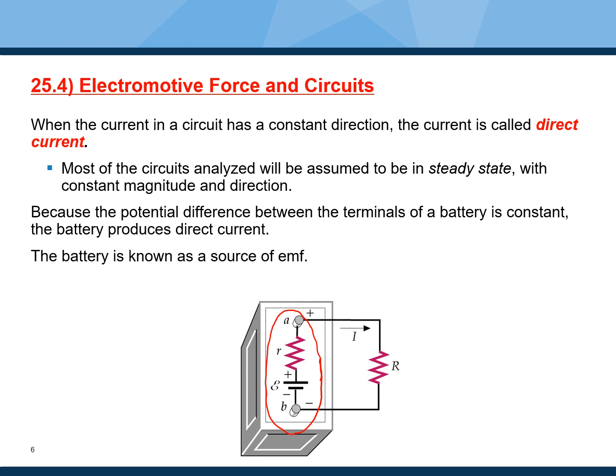And this internal resistance can in fact be non-negligible, and therefore there is some amount of energy being drained as you have current flow taking place in this internal resistance of the battery, which is why the battery heats up. Of course, the current also flows through the rest of the circuit, and hopefully the rest of the circuit is efficient. It will also heat up a little bit, but perhaps not as much.